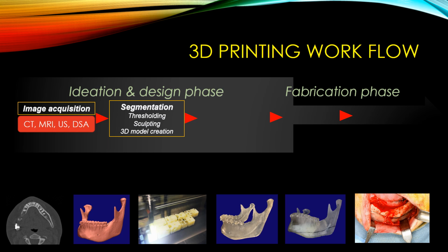Once segmentation is complete, you move to the preprint process of the mesh model creation stage. Mesh model creation involves eliminating unwanted structures, removing artifacts, and fixing surface flaws. Other tweaks required at this stage include fixing holes to make the mesh watertight, removing discontinuous portions, and joining up elements artificially separated from the model due to segmentation. Finally, structures segmented from other imaging studies like MRI or hardware components can then be added at this stage.